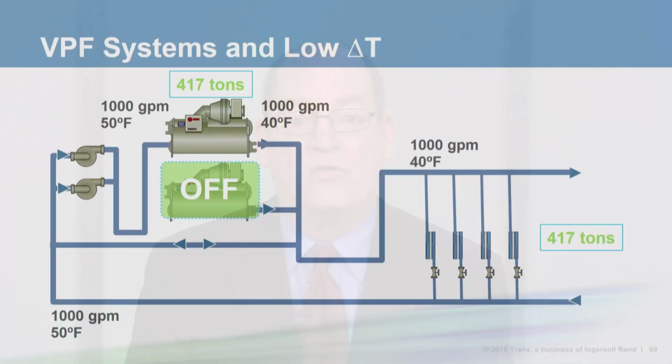This also keeps that ancillary equipment off. Here's a schematic of the overpump chiller. Note that we mentioned it was the manifolded pumps that were important. This can work in either a variable primary flow system or a primary-secondary system with manifolded pumps with variable speed drives. One more thing, overpumping is not a fix for low delta T syndrome.